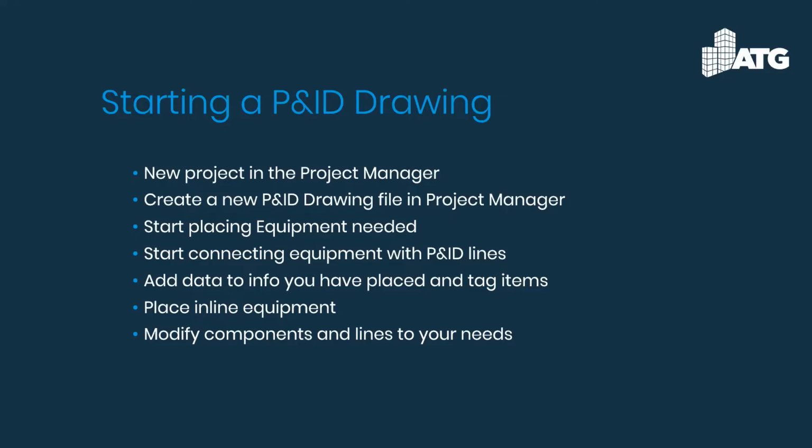Once you start up this new P&ID drawing file, you typically want to go in and start placing your equipment first, kind of getting that laid out. Then we go in and start connecting equipment with the P&ID line work.